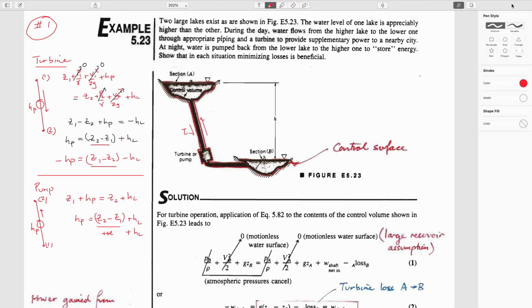The essence of that was that when we talked about conservation of mass, volume in, volume out, the difference between those equals accumulation. Either accumulation by getting a denser fluid, like in a tire, or accumulation by filling up a bucket. Conservation of momentum was just F equals ma in a more sophisticated way. But the second one, in week 7, had no viscous losses. So what we're doing now with the energy equation is admitting that in real systems, we have viscous losses.